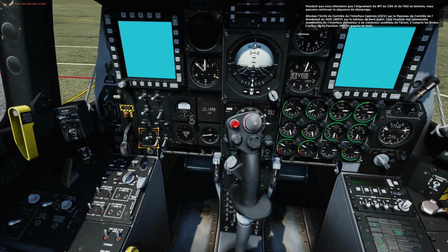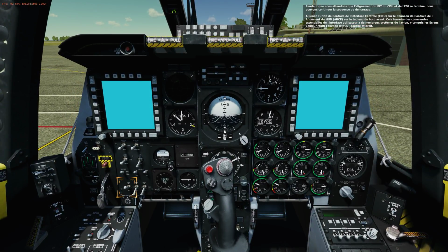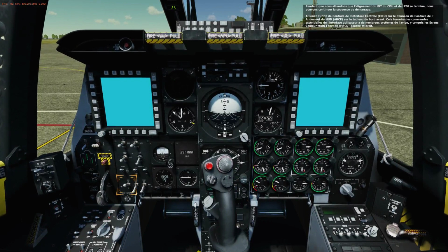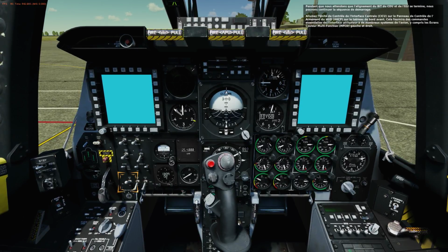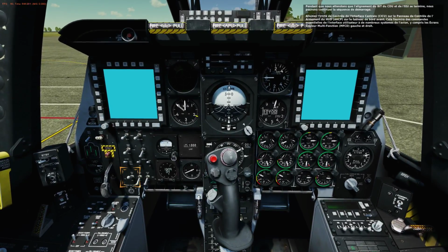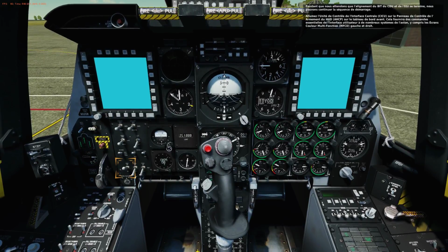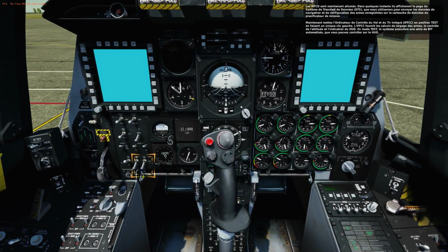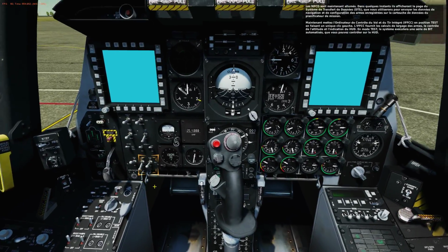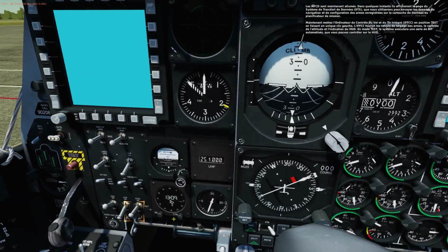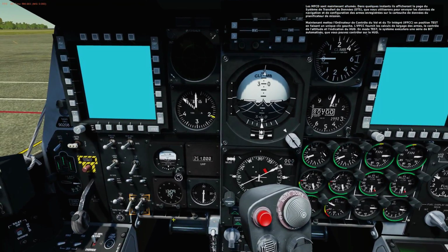Turn on the Central Interface Control Unit, CICU, on the Armament HUD Control Panel, AHCP, on the front dash. This will provide essential user interface controls to numerous aircraft systems, including the left and right multifunction color displays, MFCDs. The MFCDs are now on. In a few moments, they will display the Data Transfer System, DTS, page, which we will use to upload navigation and weapon configuration data saved on the data cartridge from the mission planner.